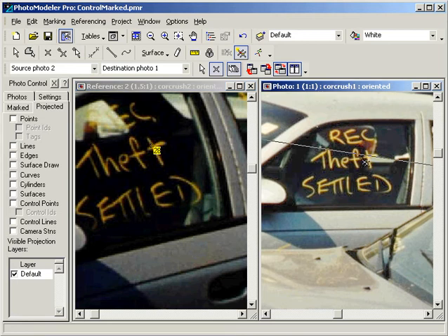The reference helper line, also called the epipolar line, appears. We can see that this line goes through the section we marked. The reference helper line helps us find the intersection where we should mark the matching point. We mark the point at this intersection.